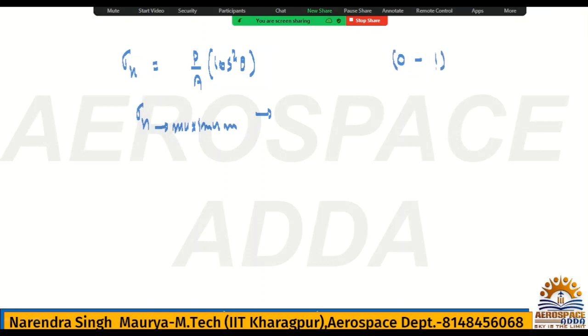So the range of this trigonometric function is 0 to 1, and the maximum is achieved when the function value is 1. That is possible when theta is 0. Simple. So your sigma n max is nothing but P by A, and that will be for the normal plane. That is the one conclusion. Now, the minimum value of this normal stress will definitely be 0, which is possible when theta becomes 90.